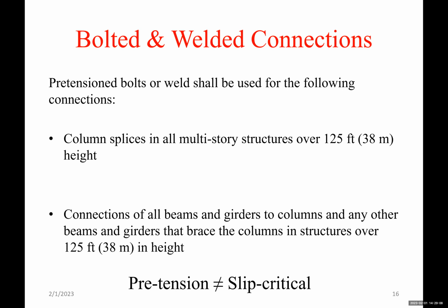pre-tension connections. Now, pre-tension doesn't mean it's slip critical. This is very important. Pre-tension bolts does not mean that the connection is slip critical, and then you have to check the capacity of the connection based on slip critical, based on the surface, the friction between the surfaces, etc. So there are pre-tension bolts, but the connection is transferring the load by bolt bearing, okay?